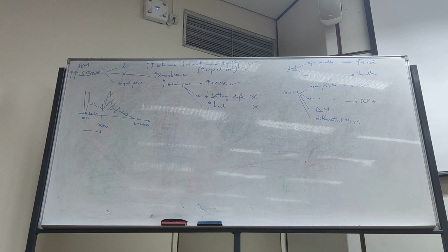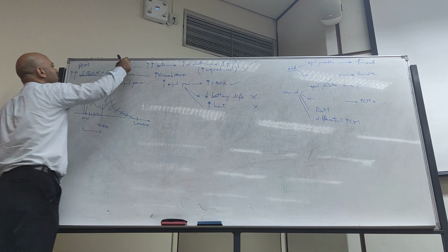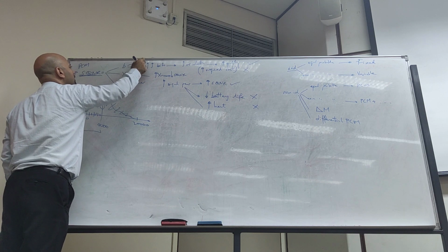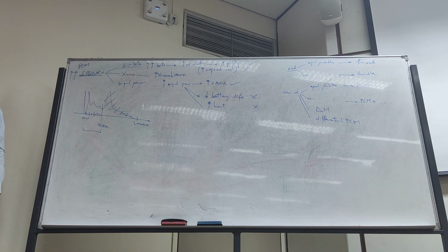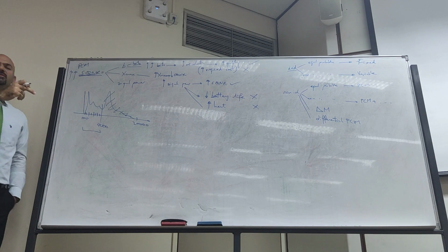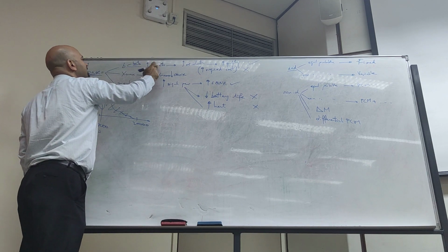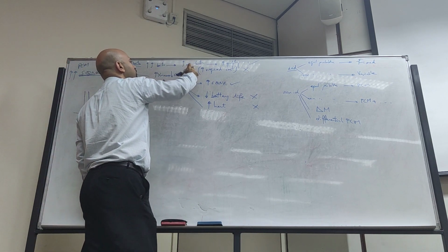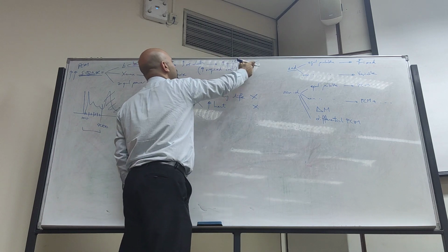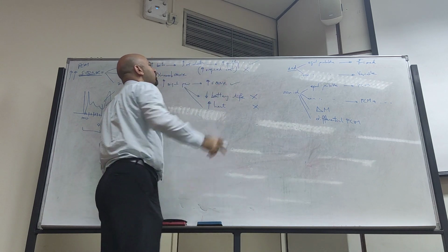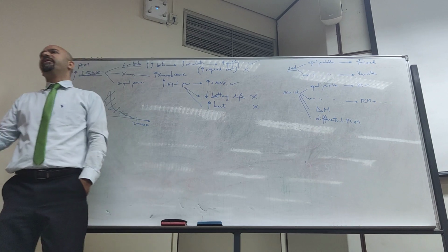But what is the B above the X max? B, and this was part of this SQNR equation. This was the bits. Next, X max. That was the range. Double B. Now, increasing the number of bits will increase the resolution, will increase the quality. This is good. But also it will increase the required data rate or required cost. This is bad.